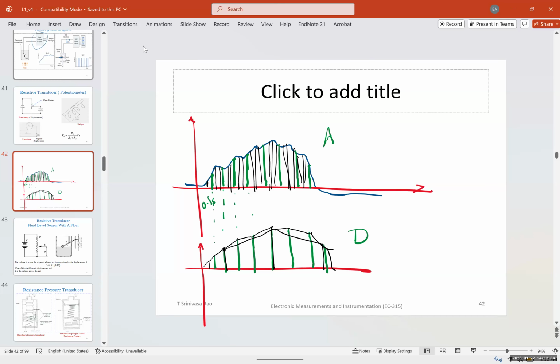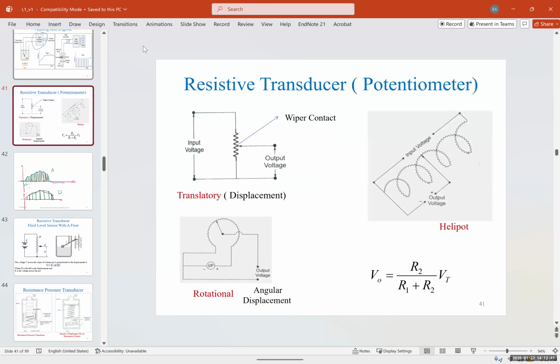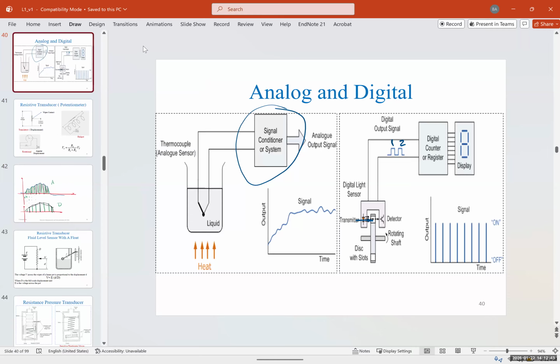What's your sampling rate, for what application? If you are measuring temperature, you don't need to do it every second. You can do it every 2 minutes. So you take a sample here, another one here. Okay? But if this was sound, you would want to take samples every 0.1 second. Okay?